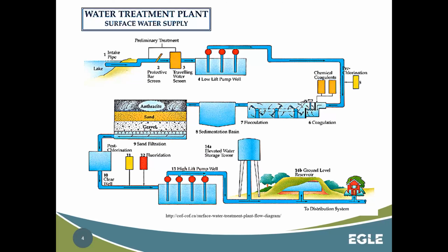And we'll have different specific gravities, different materials, right? We'll go through that filtration process. And then from there, that's our finished water, our clear well finished water. That can be where our low service pumps might need to push that water to a clear well for storage and use.